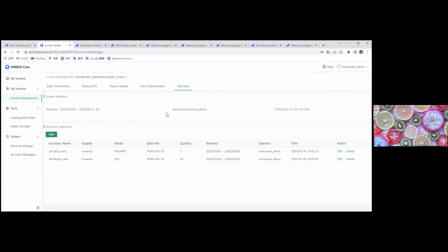is the warranty of the receiving card, module, and the branch. And the branch is very important for you. Make sure that all the receiving cards in one project are in one branch, because if you do not keep the version or the branch the same, it will cause a brightness issue, such as some modules being very bright, or some being dimmer.